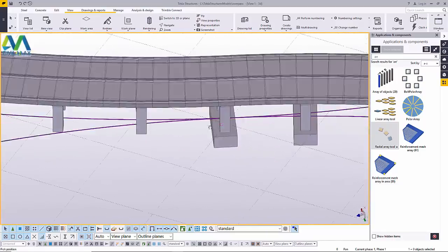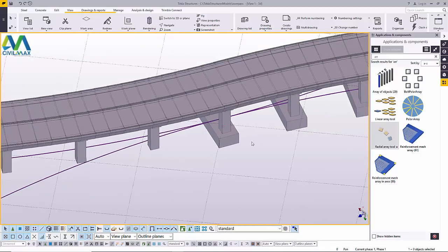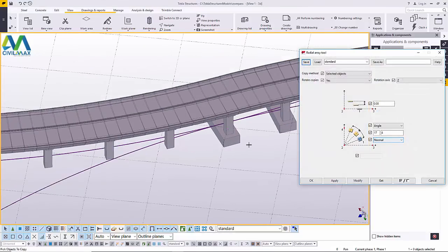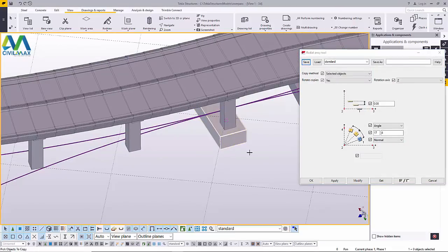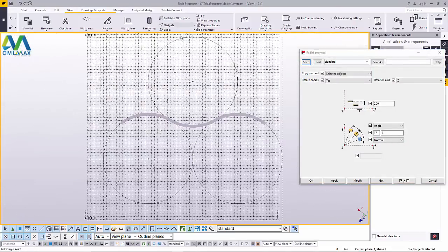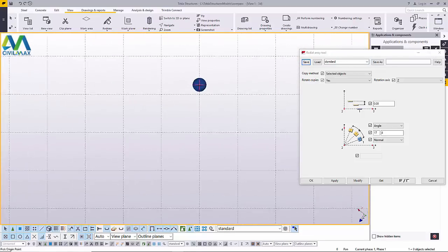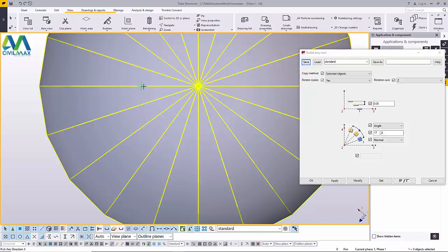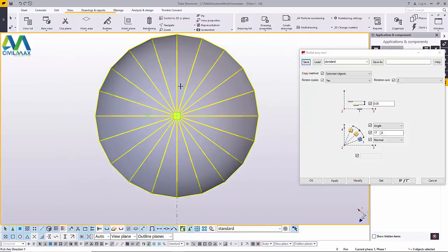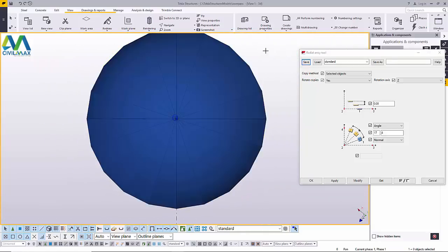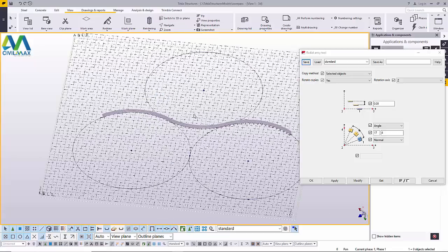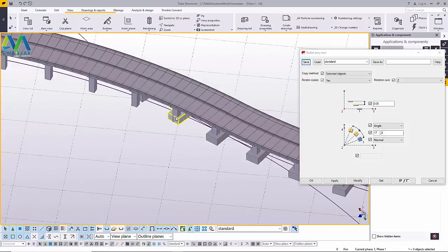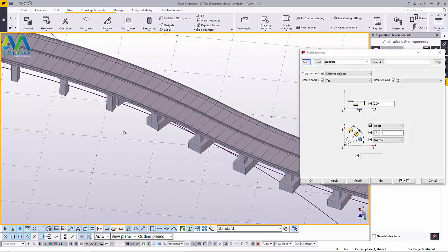And we want to continue populating this. Now I'll activate the Radial Tool and pick on this, press my middle button on the mouse and switch back to my plan view, and I want to just define my midpoint or origin, point of origin, and I'll click on that spot and define my x-axis and my y-axis right there, and press my middle button and switch back to my isometric view.